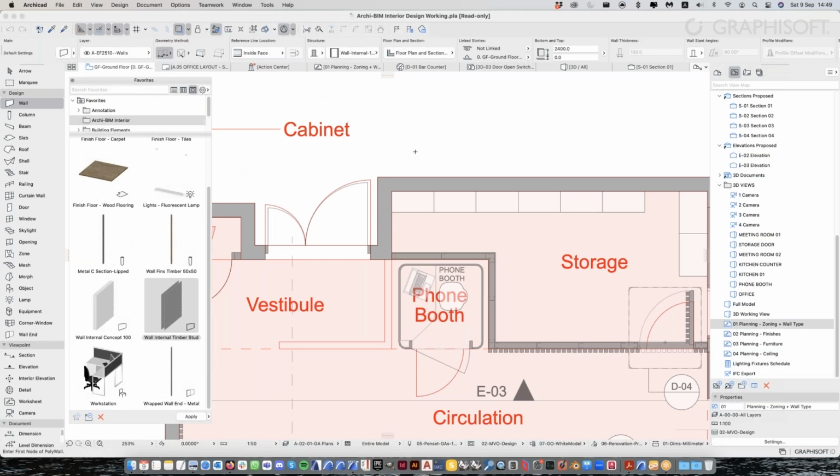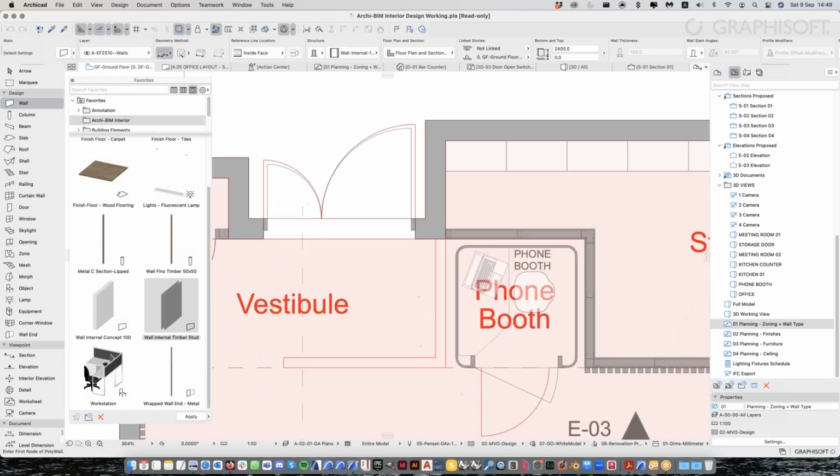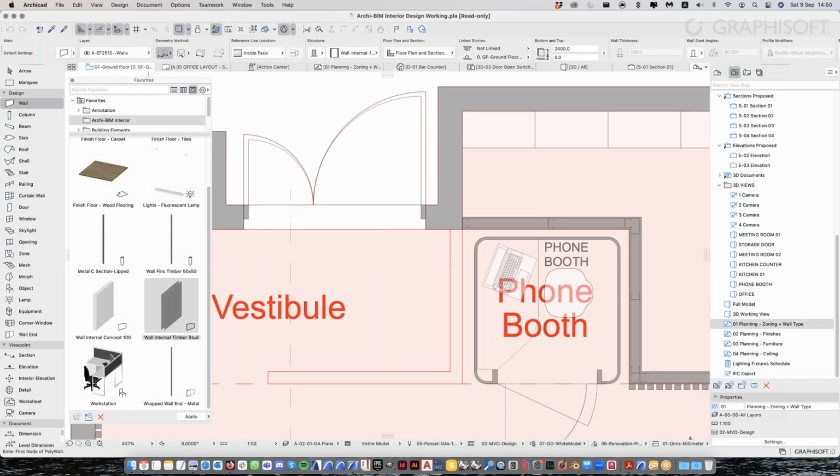Double click now. Okay, then we can start drawing. So let me just start from this point to here and to here to finish it. I'm just going to start from here. Click, one click. Okay, start. And then a second click. You will also see this kind of blue dotted line. It basically helps you snap either orthogonally or to certain angles that you can set, like maybe 45 degrees or 90 degrees. So it really helps you make sure that your model is modeled very cleanly. So the second click would be here.